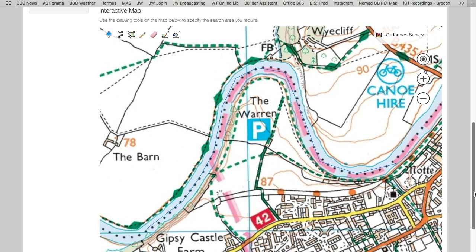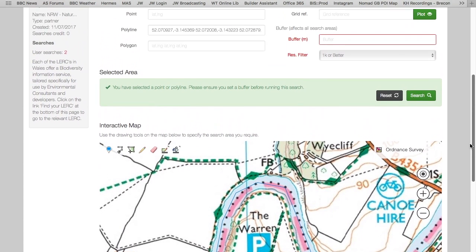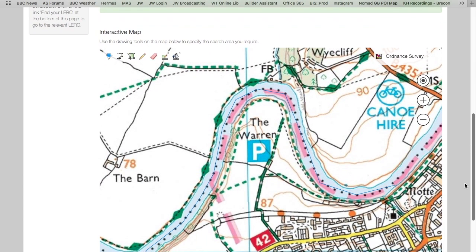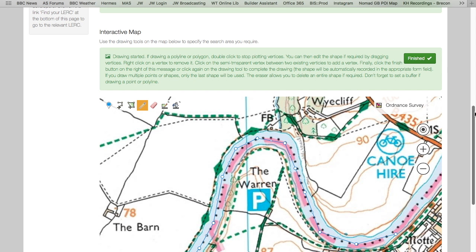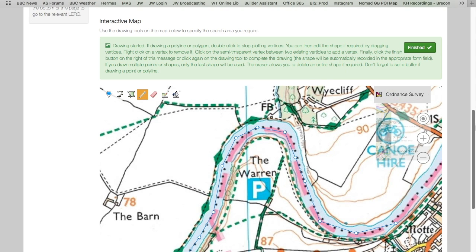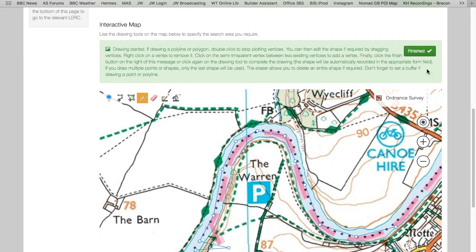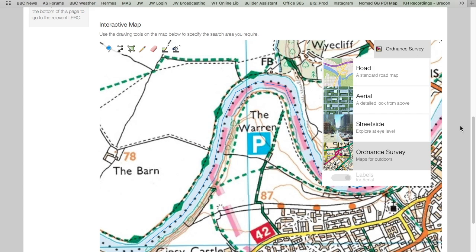Now let's assume that you've clicked Finish, but now you realize that you want to edit that line, or indeed the polygon that you've put in. It's exactly the same for polygons. You can now select the Edit tool, find your line, click on it once, and there you'll see that the drawing has been started again, and you can now edit these nodes again, and maybe add some extra nodes, or whatever you want to do. Again, once you've finished the editing, you can click on Finish.